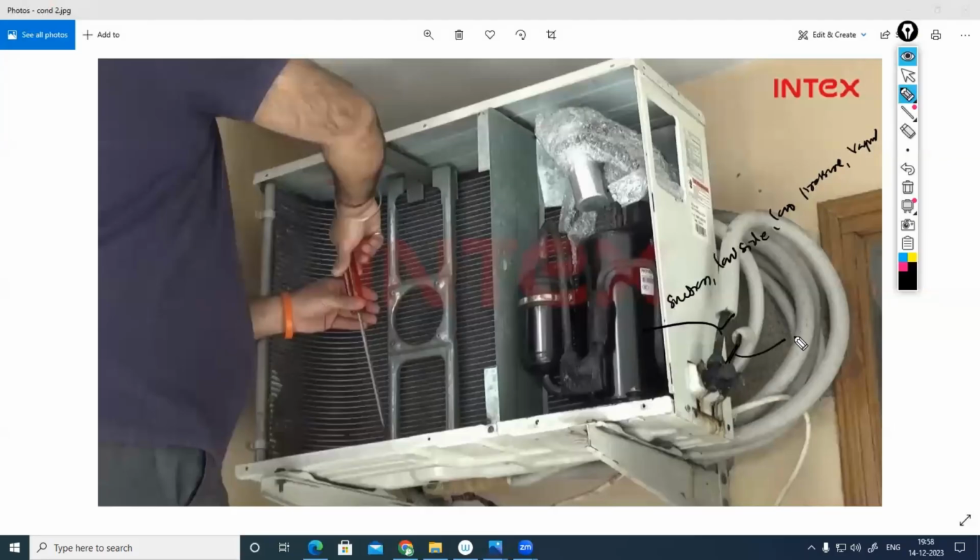This one is called the delivery line, discharge line, high pressure line, or high side line, different names. The smaller diameter is liquid only. You can imagine this is vapor. The density of liquid is always higher than vapor, so liquid needs less diameter than vapor. That's why the smaller diameter is indoor to outdoor. That is liquid. Outdoor, evaporator to the compressor.